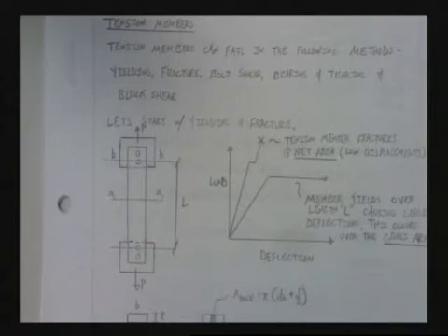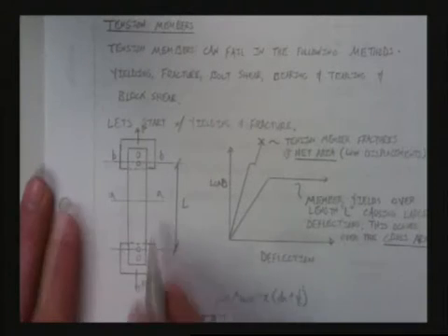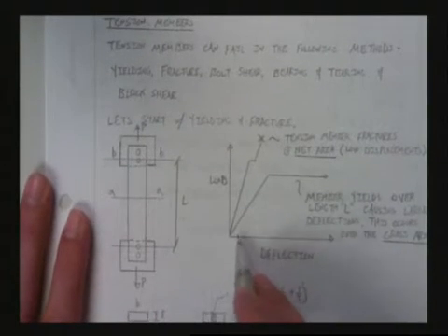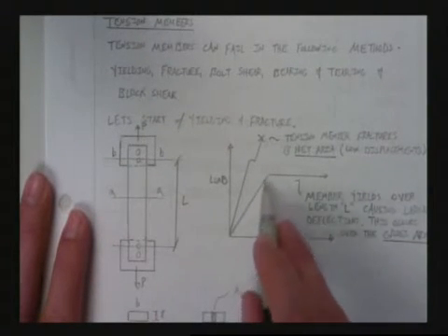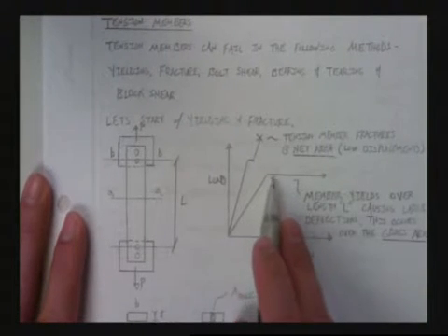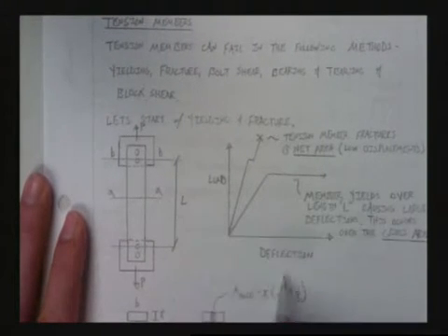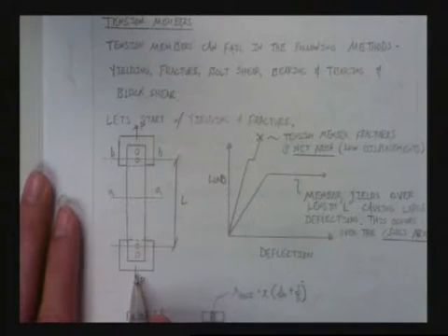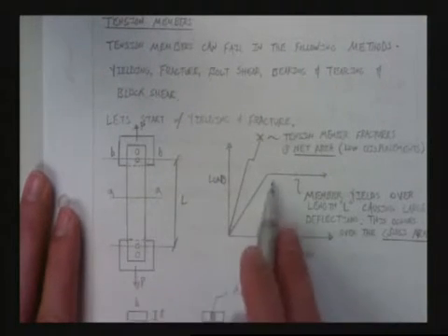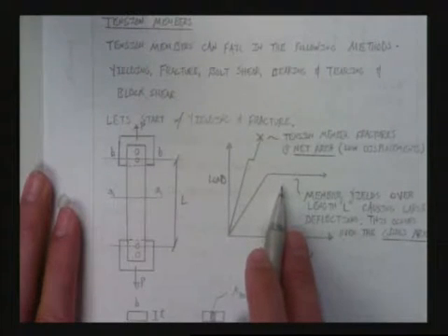It's actually where things fail when they yield. And we're going to show a movie of that in just a second. When things yield, they go up and they go up and they go up, and then they hit this plateau and they just go and go and go. This is load. This is deflection, right? If you are holding on to the bottom of this and you reached yield, what's that going to feel like for you?